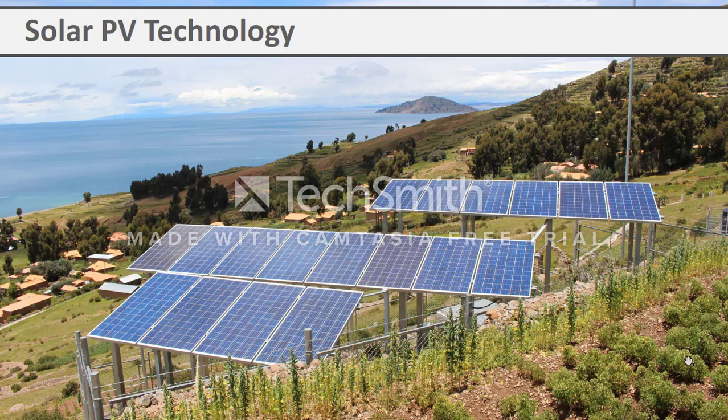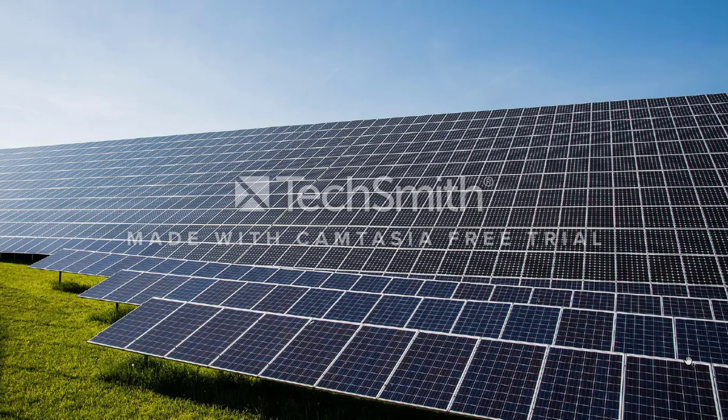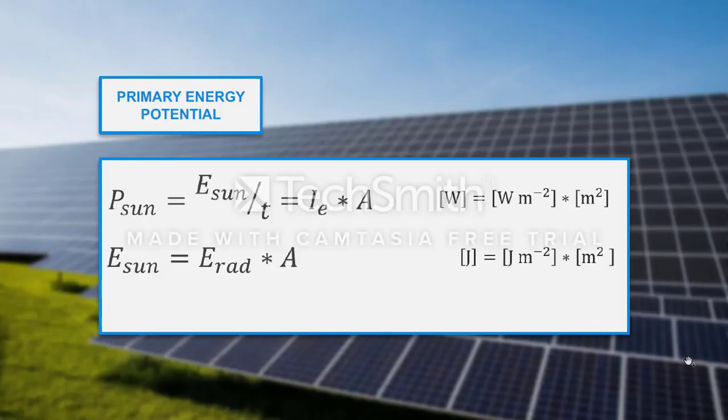We can characterize the power of the sun by the irradiance. Irradiance means the amount of energy per second incident on the surface of the earth per meter square, and therefore it is expressed in watt per meter square. In order to find the potential of the solar energy, we can integrate the irradiance over a certain amount of time to obtain the irradiation. The total energy potential of the certain PV panel is equal to the product of the irradiation and area of the panel A. The solar irradiation strongly depends upon the angle of the sun with respect to the Earth's surface.